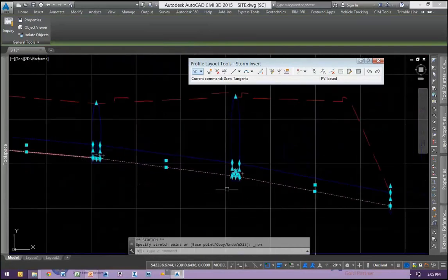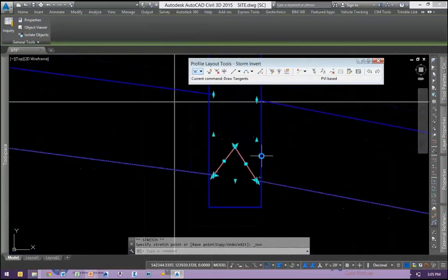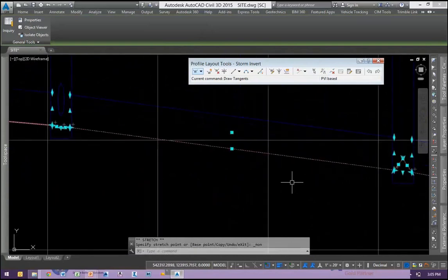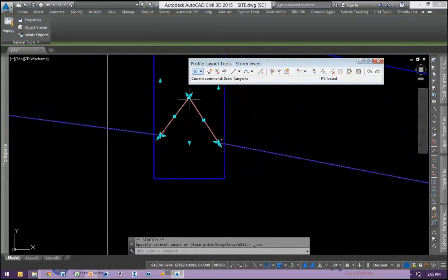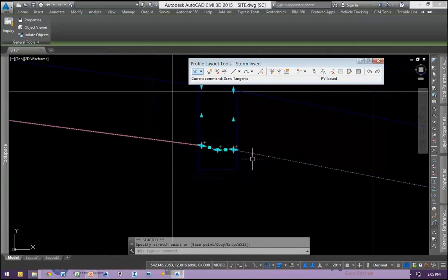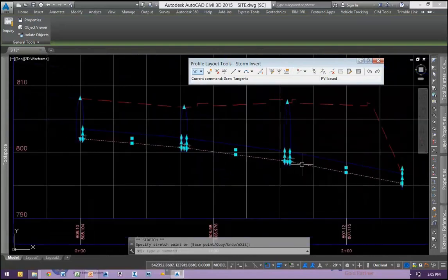Okay. So what we can do is now stake anywhere along this. That gives us invert a pipe. And we can also stake center, invert a structure. Okay, so the surveyor would be able to toggle right through that stuff. It's pretty foolproof. It's alignment profile on the drawing. We don't have to think about invert between this structure and that structure.